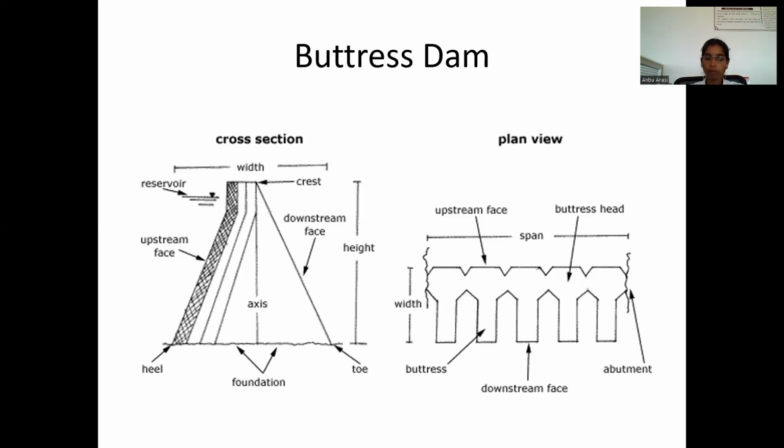Additional skilled labor is required to create the framework. Threat of deterioration of concrete from the impounded water is more likely than from a thick gravity section. There is also an elimination of a good deal of uplift pressure.